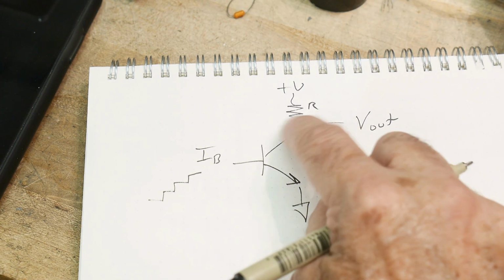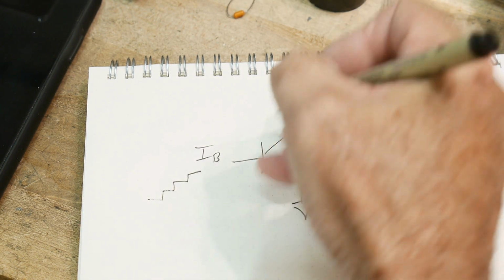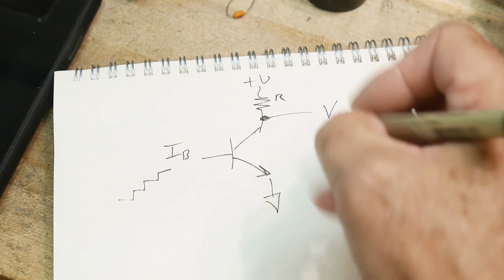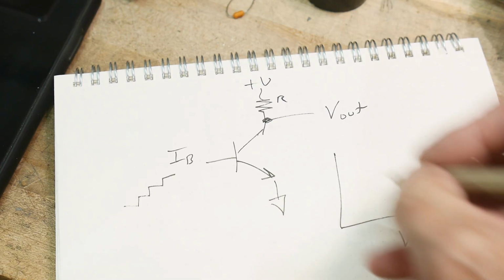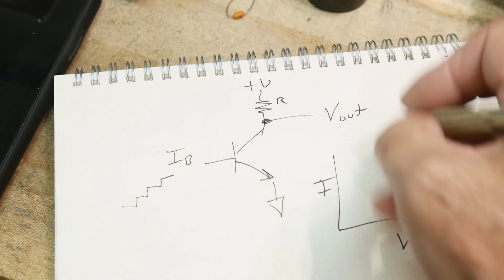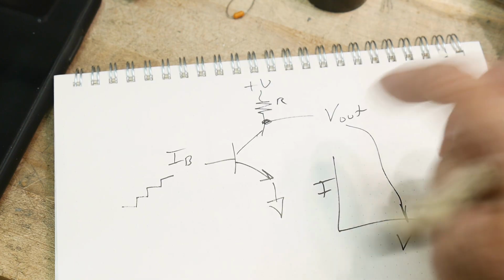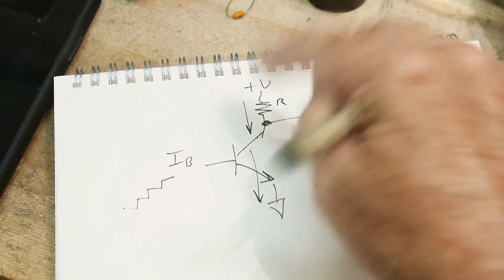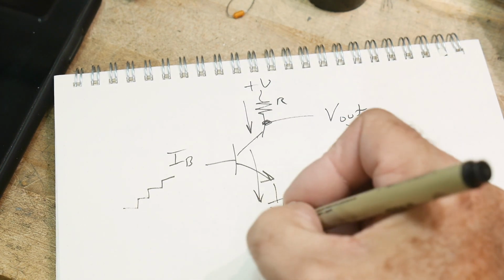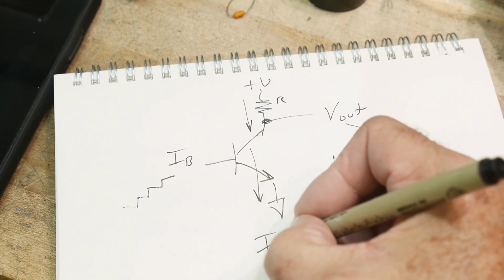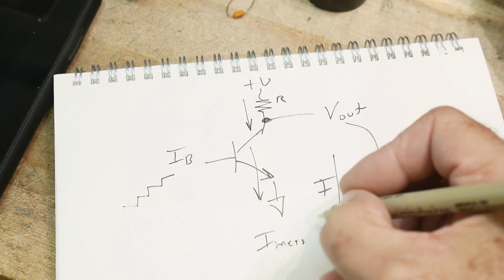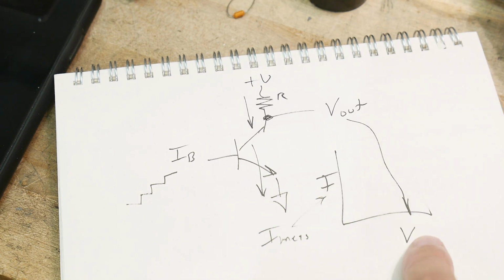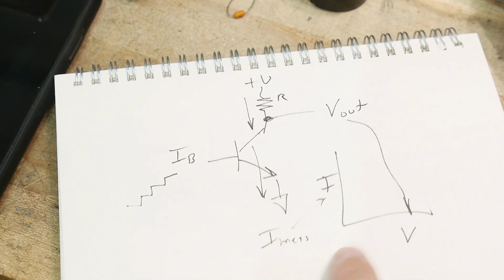We get to choose whatever resistor we have in order to match the circuit that we're trying to evaluate. And then we monitor the voltage, and so we get a picture of volts versus current. This is the volts that's going to be measured, and the current that's going to be measured is the current through the whole string here. This is the current we measure, and that's the thing that we graph here. So we get a graph of voltage out and current through.